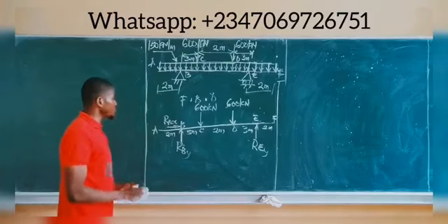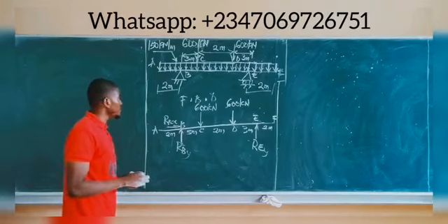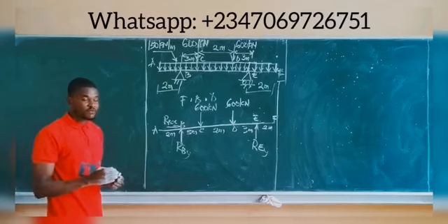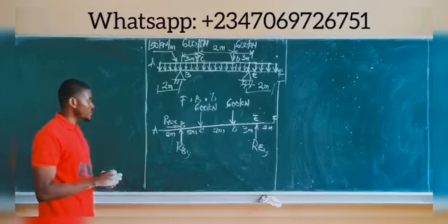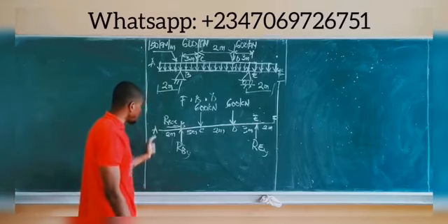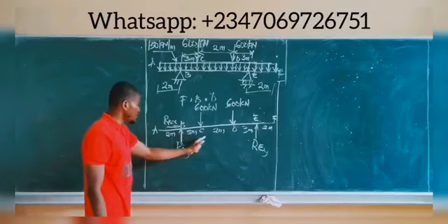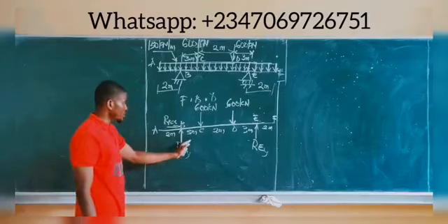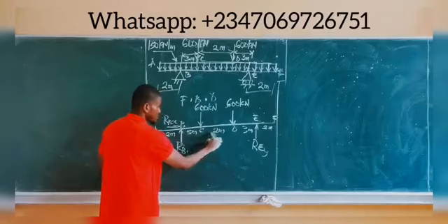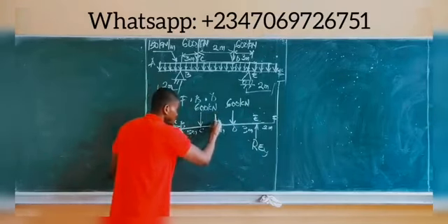And if you're placing this load, you place it at the middle of the length carried by the beam. If 12 is the length, then the middle is simply 12 divided by 2, that should be 6 meters from point A. So from point A, we measure out 6 meters. From A to C is actually 5 meters, because this is 2 plus 3, that's 5. So 6 meters is found at the middle of C to D, because from C to D is 2 meters.